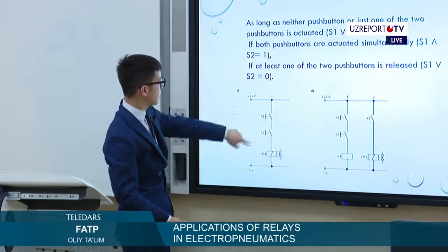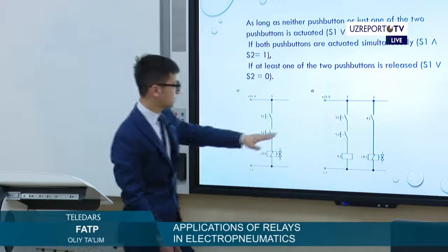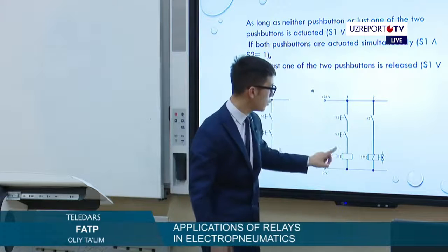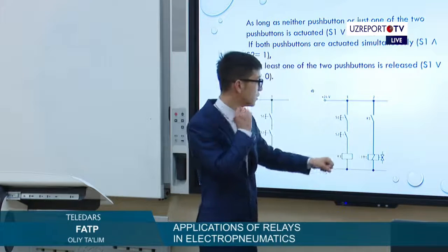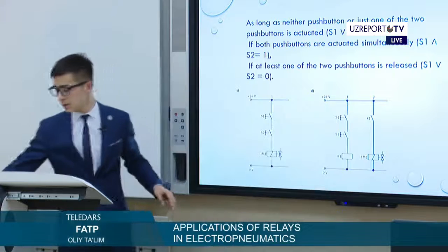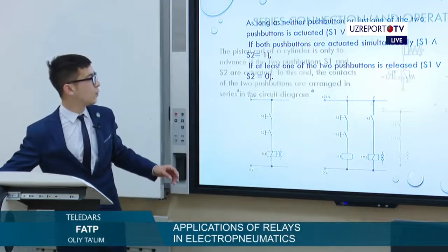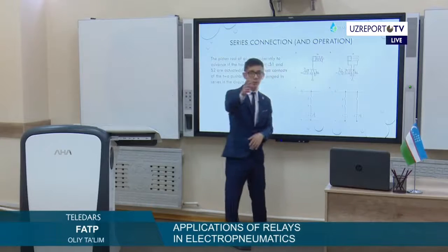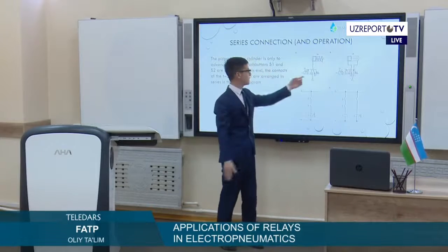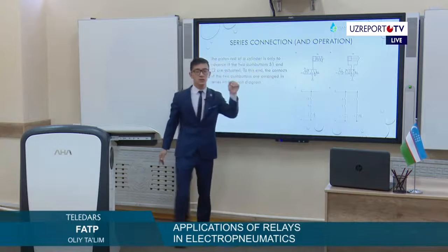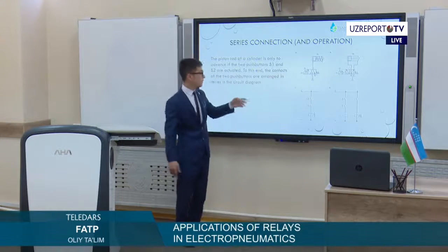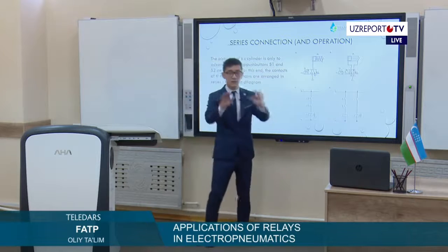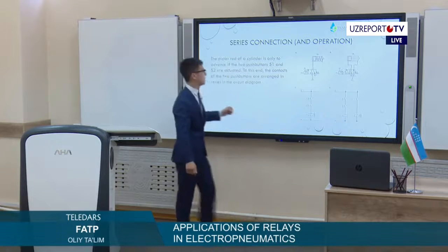Here you can see that they are put in one line. And in D, all the voltage comes to the coil, and then the coil connects and works the pushing machine. All these operations are in a double connection like before, for OR and AND. We use the same pressure machine as an electropneumatic unit, they're the same, but the connection is just changed with the use of the AND element and the two push buttons in one line, not in parallel form, only in one line.